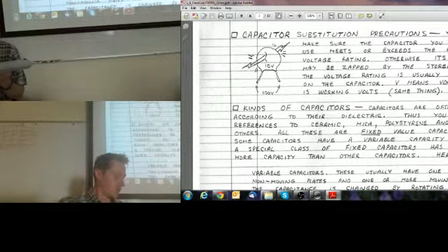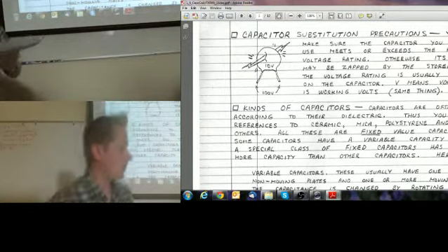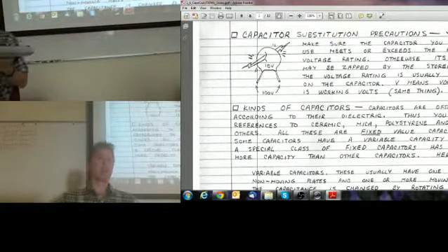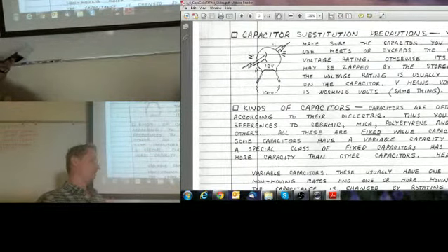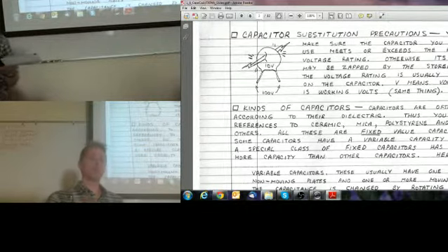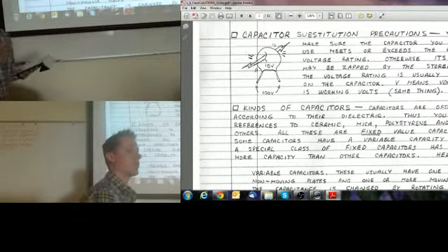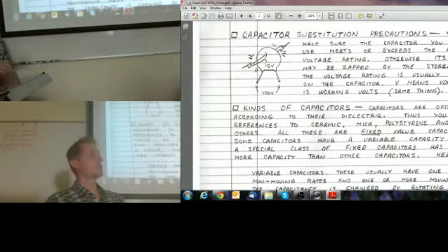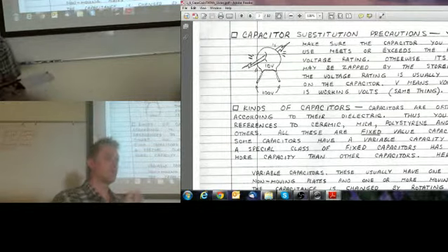So also remember, when you're dealing with capacitors, many times if you look on a capacitor in an old TV or something and it says 200 volts on it, you probably don't want to touch it. Normally we will choose twice the rating of what we need. So if we need 100 volts across the capacitor, usually we would get a 200 volt capacitor.